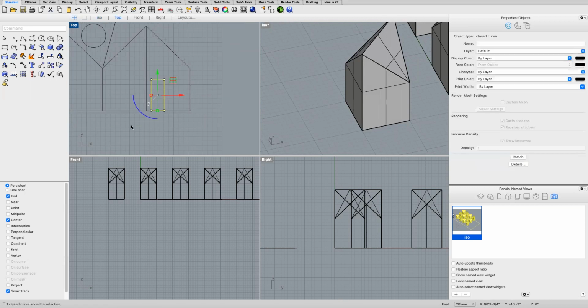So you select what you want to orient. You type in orient, but instead of orient, you want to orient 3 points. So now instead of 2 reference points, you've got 3 reference points, which makes it a little trickier. But you got to remember, it's got to be the same exact order. So I always do the corner and then I go X and Y. I just try to keep it consistent.